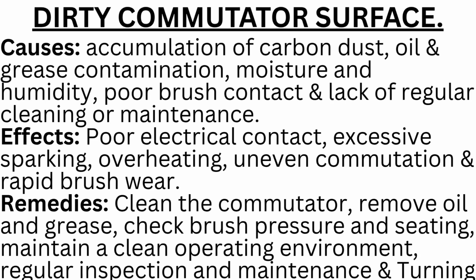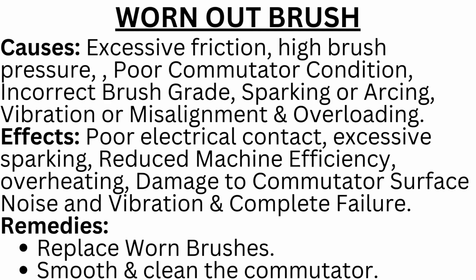Causes. Accumulation of carbon dust, oil and grease contamination, moisture and humidity, poor brush contact and lack of regular cleaning or maintenance. Effects. Poor electrical contact, excessive sparking, overheating, uneven commutation and rapid brush wear. Remedies. Clean the commutator, remove oil and grease, check brush pressure and seating, maintain a clean operating environment, regular inspection and maintenance and turning. The next maintenance failure is worn-out brush.